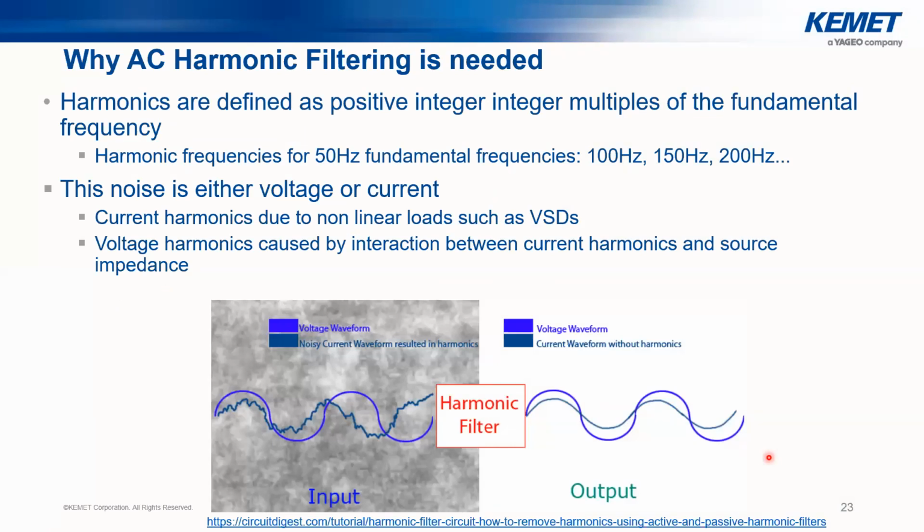Moving on to AC harmonic filtering. The reason why I included a couple of slides on this topic in this presentation is mainly because we have seen many customers or many engineers using an X or Y rated capacitor series also for AC harmonic filtering. Well, the purpose of an X or Y capacitor is much different from that of an AC harmonic filter.